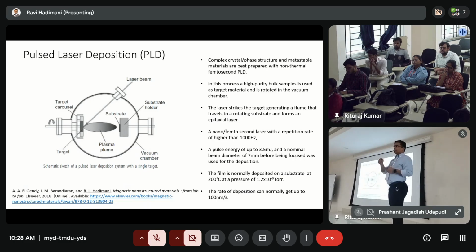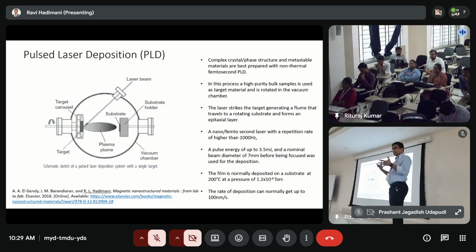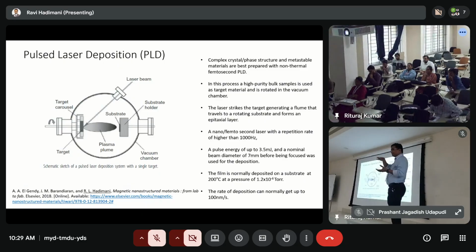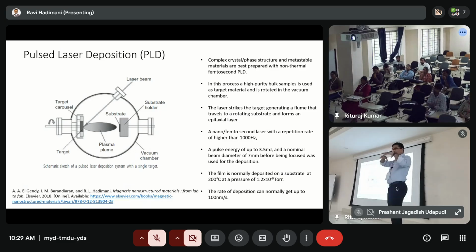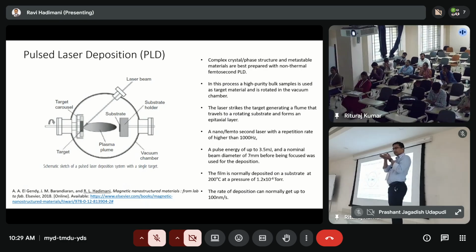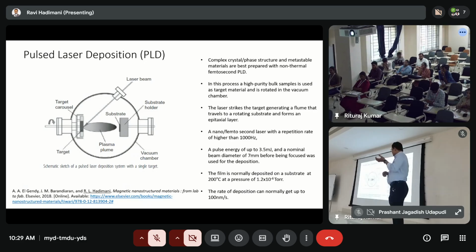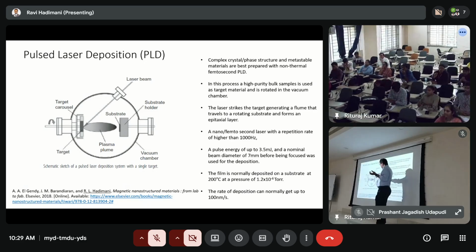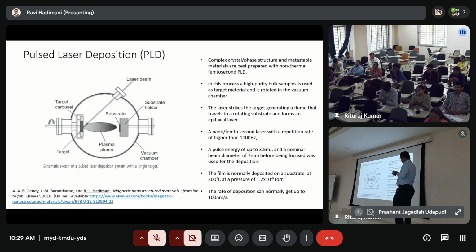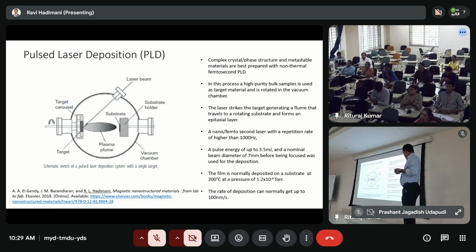And when they go up and come down, what happens is they release a phonon. And phonon is nothing but the vibration. The phonon is what results in heating. So the vibration, the phonon it generates in the material heats that material in that place. And this is very local. We're talking in terms of a few microns. That's how nanosecond laser works.